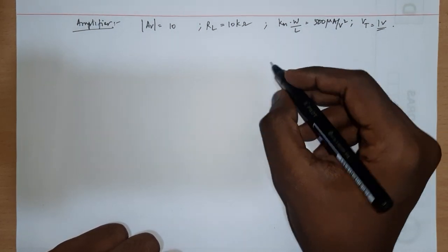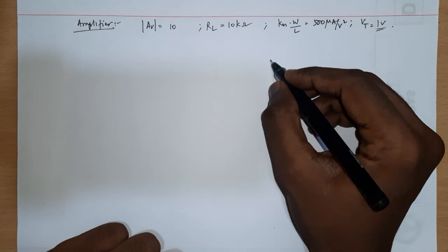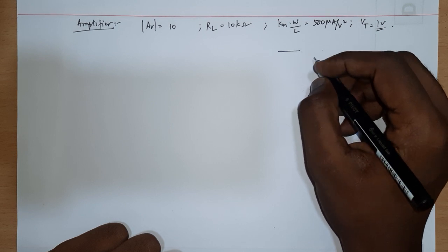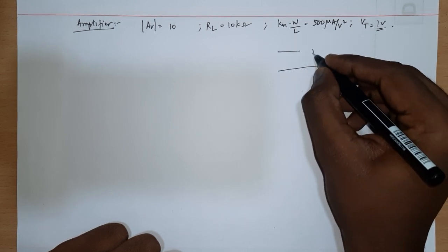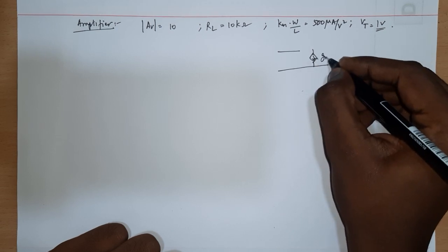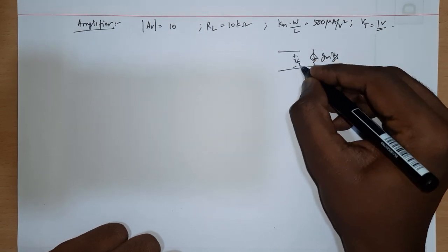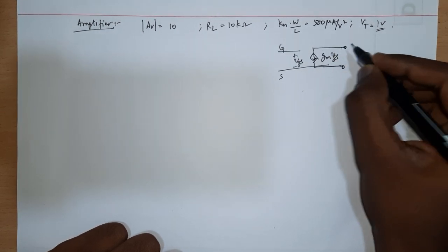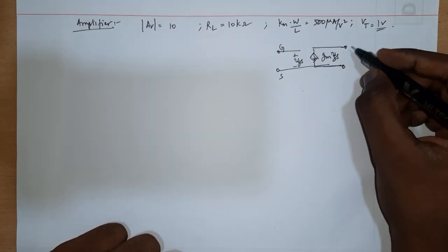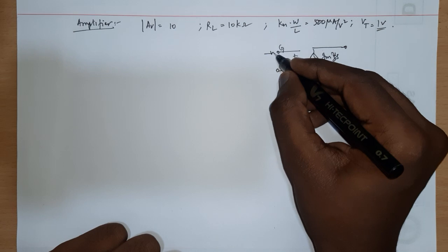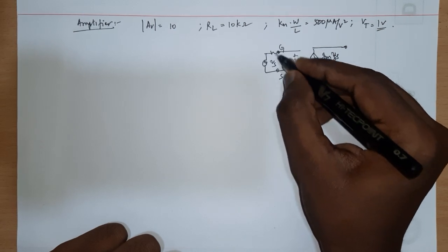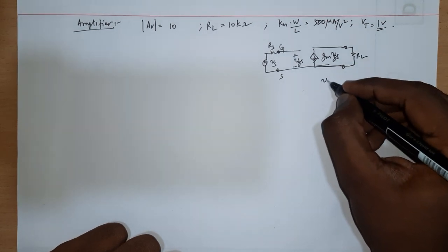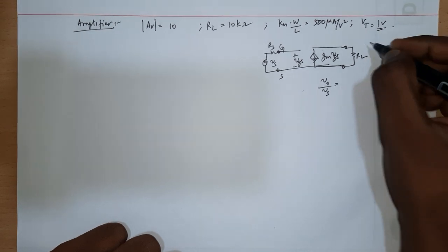As per our discussion in the last lecture, this MOS transistor in its native form, the incremental equivalent will look something like this: GM VGS, where this is VGS, between G and S. Here is where you give the input, and here is where you take the output. If your input source is given in this way, and your load is connected in this way, then you are going to get a gain V0 by Vs, where this is V0.